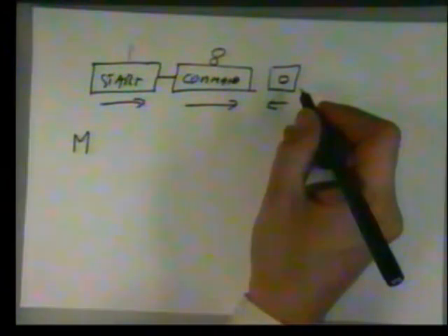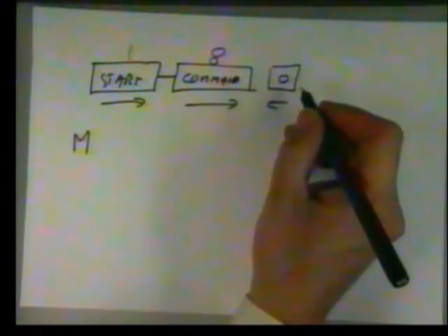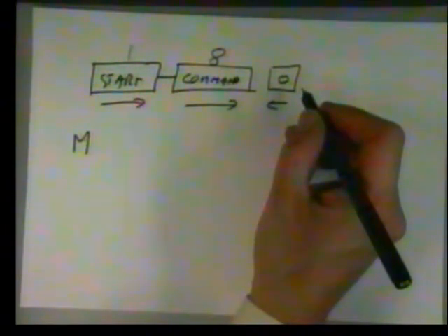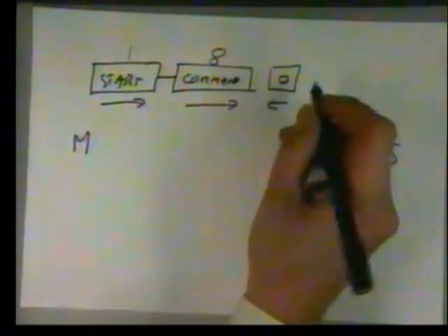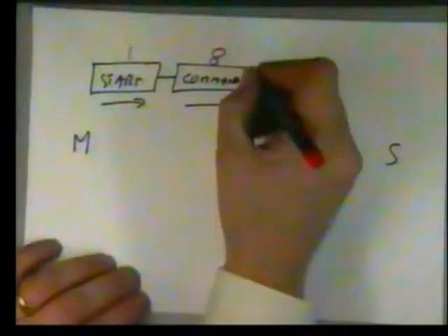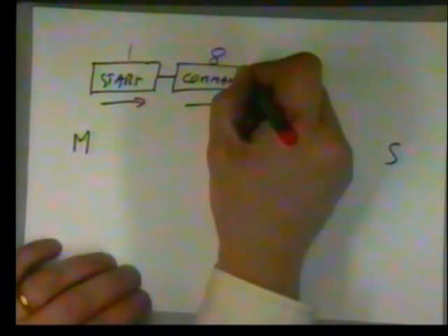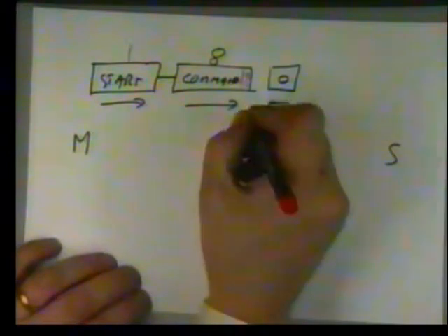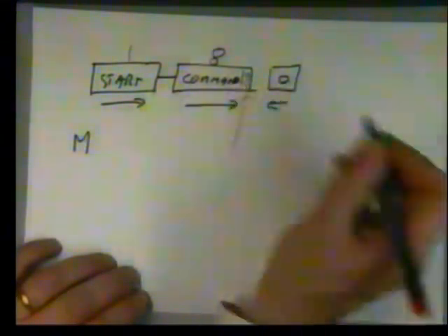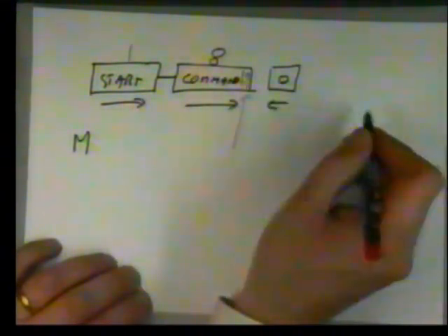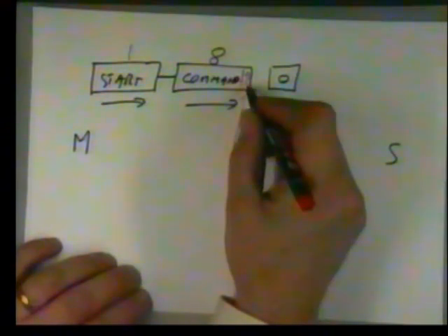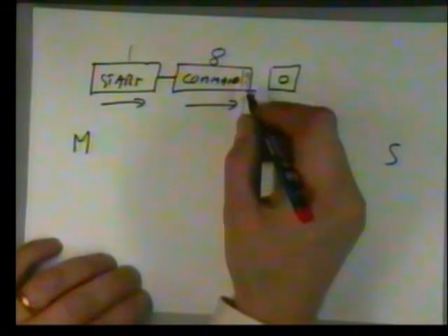So, what happens next? Well, this is always determined by the contents of the least significant bit. It could be a 0 or a 1. That bit tells the receiver whether or not the next operation is a read or a write operation.